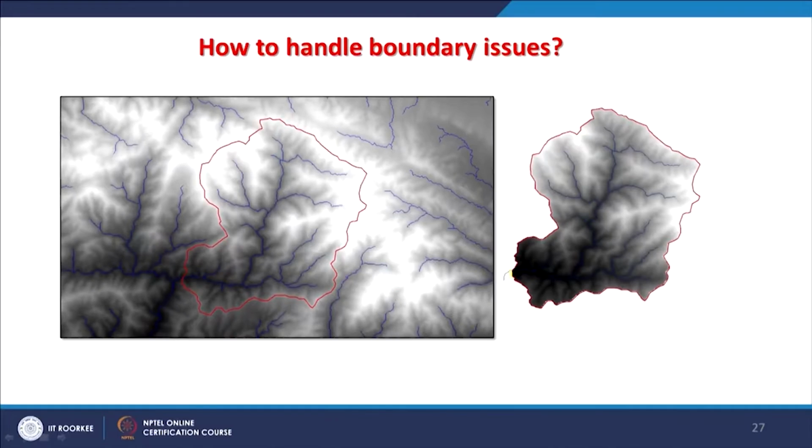One important point which I want to bring here is to recall the discussion related with no data. So, this watershed must have a rectangular area like this, but here the outside of my watershed is being represented through no data, and no data has been assigned by default, or you can assign a background value on your screen. Generally it is white. So, then I will not see any no data; I will see the digital elevation model or my drainage network only for my area of interest. So, this is how these things work very well.